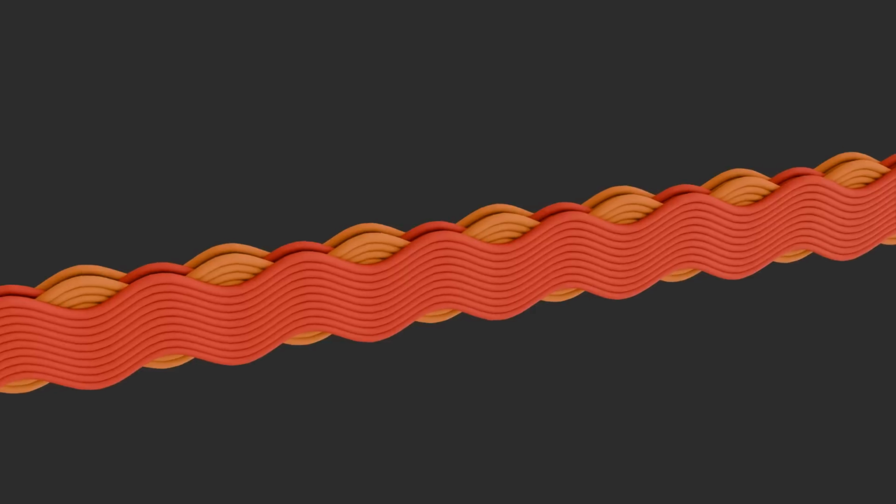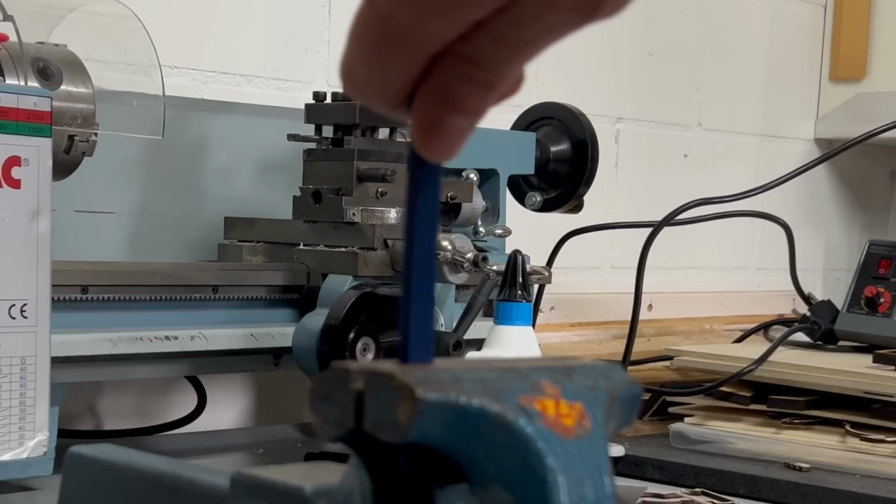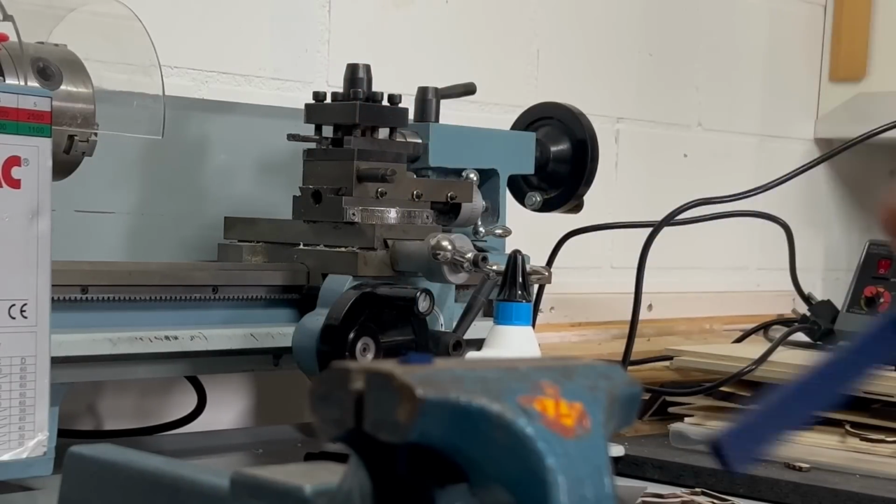But here comes the reason for the title of this video. I coded it so that you can enable that the sine wave alternates between wall loops. This results in an overlapping pattern and removes thorough clear breaking points on the layers. I'm not equipped to do testing myself, but it sure does feel stronger, as you can see here.